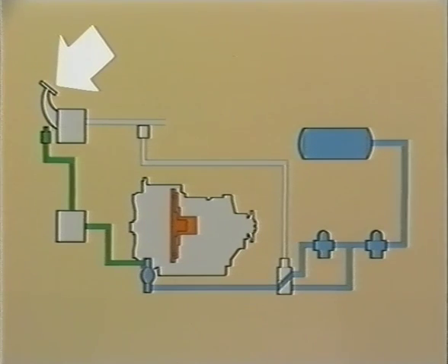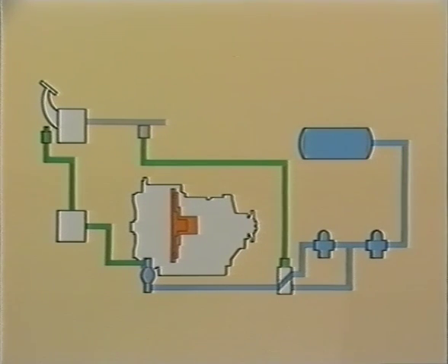As the foot brake is depressed further, an air pressure switch located in the rear brake line is triggered when the pressure reaches 7 pounds per square inch. At this point, this EP, known as MV4, is energized, which now allows air through at 3 bar to the retarder valve. This increased air pressure enables a higher oil pressure to be supplied to the retarder unit at a pressure of approximately 4 bar.